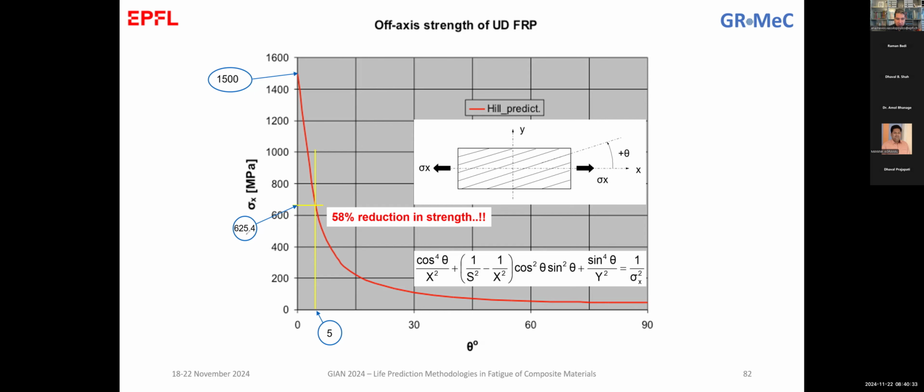And this is an indication of the sensitivity that we have with composite materials and the patience, if you want to call it like that, that a manufacturer should show when they lay up the material configuration. If you just do a slight misalignment because this day you're not very happy, you are not very consistent with the manufacturing, you can cause problems like that. You actually build a material system that is assumed to have very good properties, and at the end of the day, it doesn't have good properties at all.